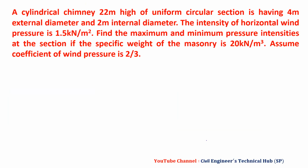Now in this we have a cylindrical chimney 22 meters high of uniform section. The uniform circular section has a 4-meter external diameter and a 2-meter internal diameter. The intensity of horizontal wind pressure is 1.5 kilonewton per meter square. Find the maximum and minimum pressure intensities.